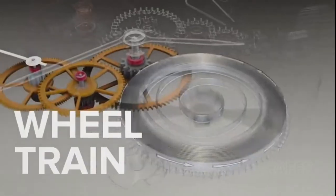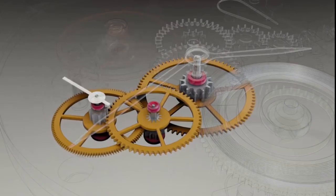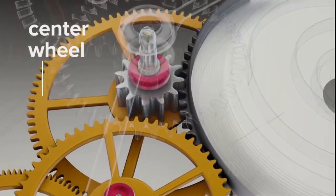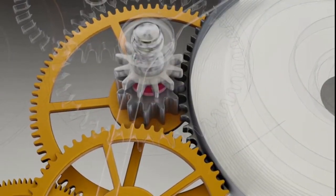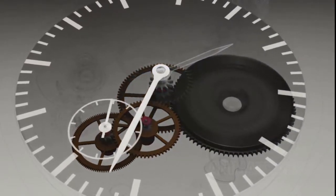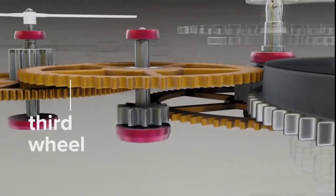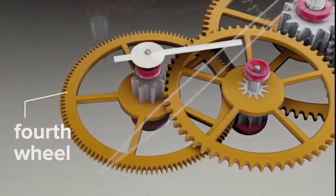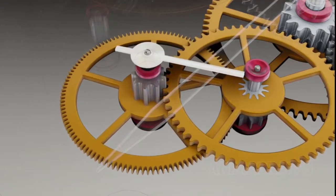The wheel train. The wheel train drives time-keeping hands and associated wheels. The center wheel is driven by the mainspring barrel and rotates once per hour. It holds the minute hand, and its 60-minute journey is often divided up into minute marks on the watch face. The third wheel flows power through to the fourth wheel.